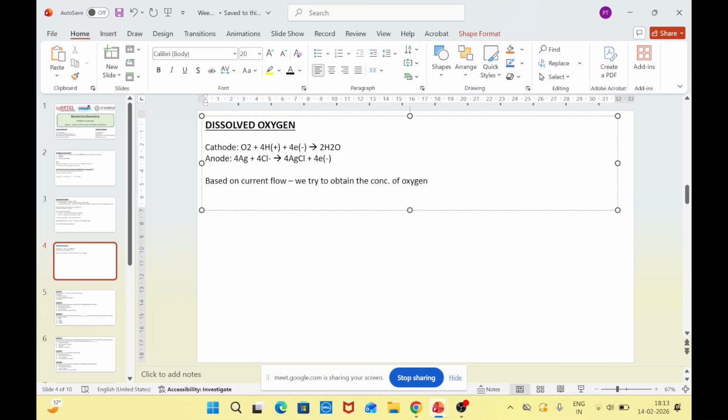So this is the principle of how you see the dissolved oxygen. We have a standard, and based on that standard, we know that if this much current comes, then this will be the particular oxygen concentration. Based on the shift in the oxygen concentration, the current will be affected. Based on that change in the current, we can correlate to the change in the concentration of the oxygen in the system. Next is the glucose monitoring system.